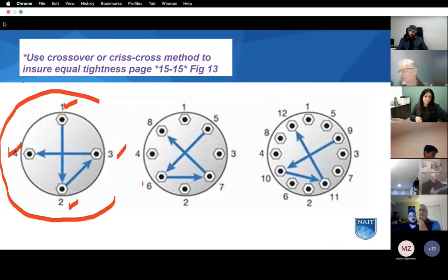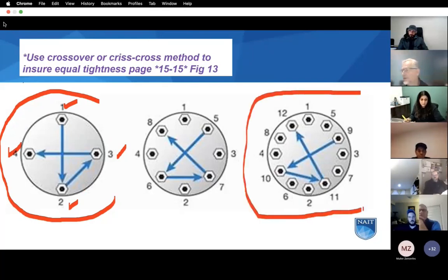When you tighten up the stud nuts on your vehicle wheels, you should use the same method. You tighten them hand tight in a crisscross pattern, and then you use that recommended pattern again to go to about 1/3 of the maximum torque. Use the pattern again to go to 2/3, and then, depending on the procedure, very high pressure flanges with numerous bolts will go up to 90. It'll be a 4-step process, 90% of maximum torque, and then again to 100%.